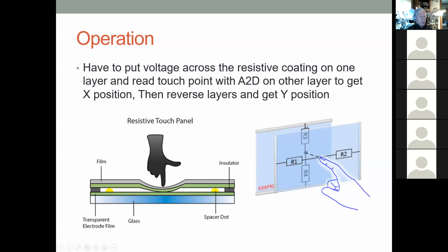And you just do that very rapidly. We're currently averaging, I believe, 32 readings, maybe it's 16, because the A to D converter will automatically do that for you. It will read the same input, say 16 times or 8 times or 4 or once or 32 times. You get several selections. And I think I'm doing 16. So it reads it 16 times and averages them. It may be 32, I don't remember. I'd have to go back and look at the code.